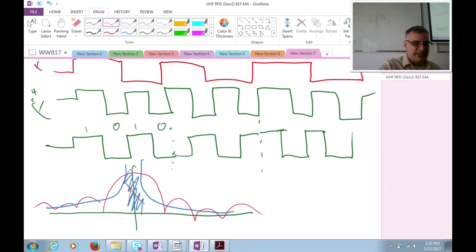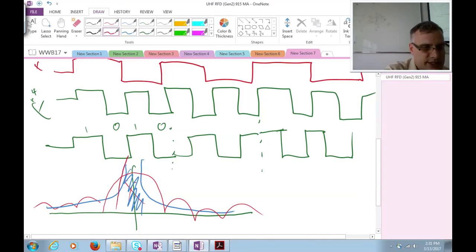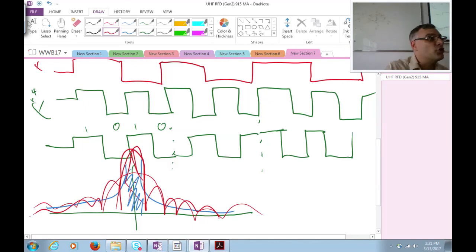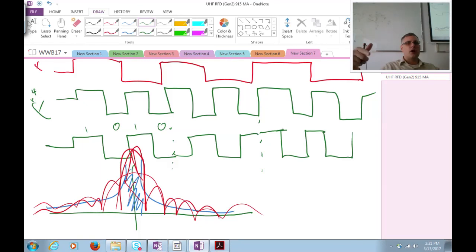Why? Because look at the diagram here. If I decrease my signal rate, more and more of my signal concentrates in this area where noise and interference accumulates. My signal to noise ratio gets worse most of the time in that scenario, not better, like it does in a regular wireless link that has nice additive white Gaussian noise that's limiting communications. So what the subcarrier modulation does is allow you effectively to slow down your data rate. You're exchanging power consumption for fidelity in your data signal.